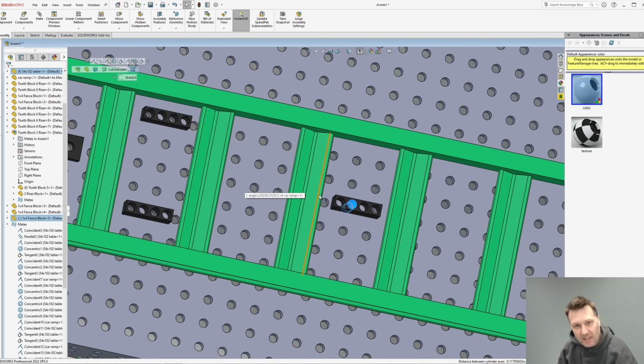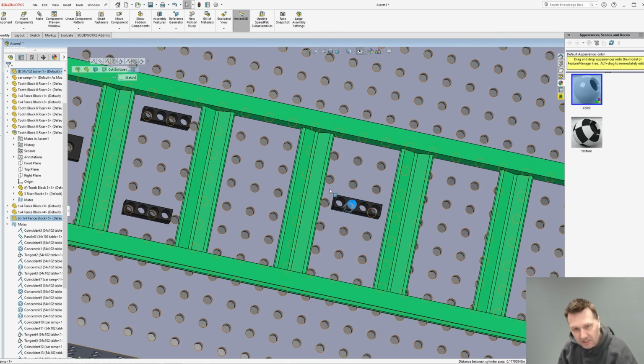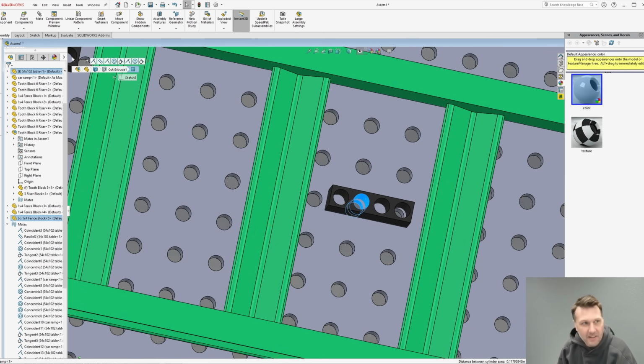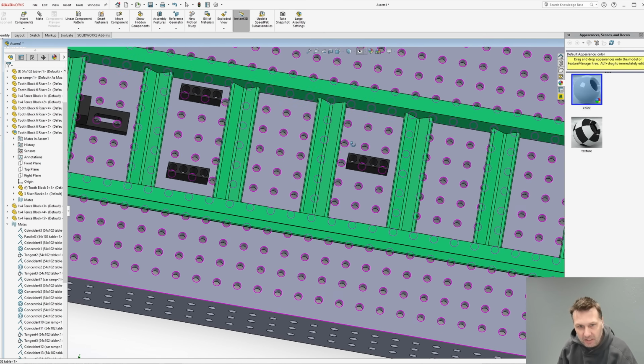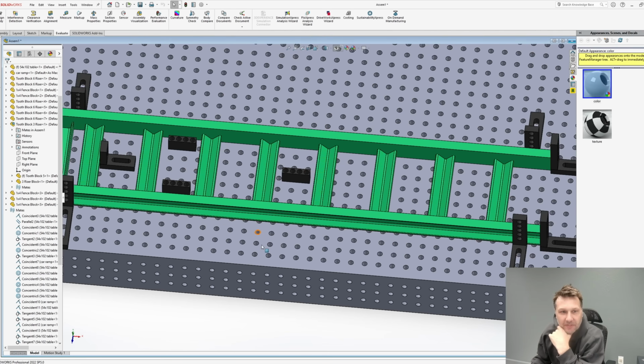And you can also line these up with a grid and the table. You can kind of sight down it. It just depends on how accurate you want. So there's another solution. Just put 1 in the middle, shim off the back, shim off the front, and that gives you your distance.